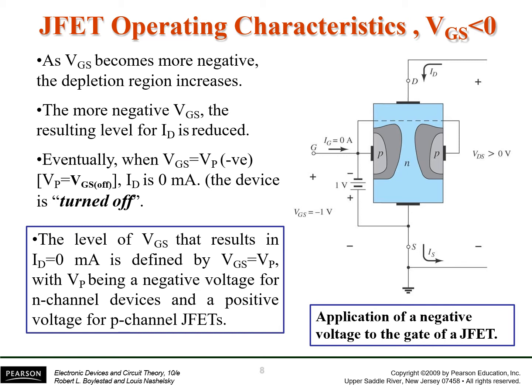That particular value of VGS at which the current ID cannot lift itself from 0 is called the pinch off voltage, or VP. That is the second important characteristic of a JFET, right? So these are the two basic characteristics of a JFET: IDSS and VP.